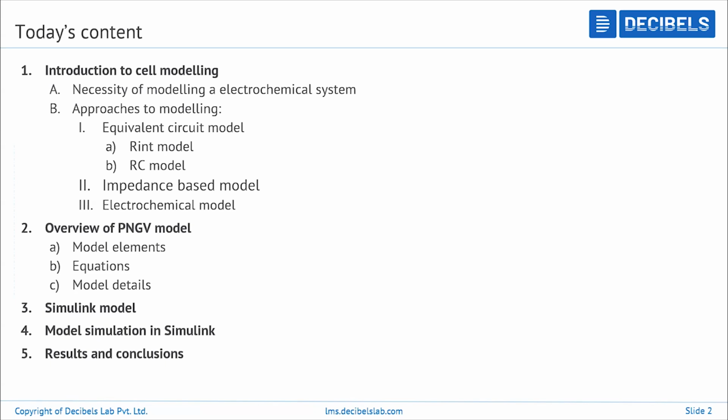Next, what process of a lithium ion cell does an RC battery model represent? Mainly we are representing all the processes inside of the cell as electrical elements like resistors or capacitors. Later on we will see how they're built. The fourth one, which model type is preferred for simplicity? Always it is electrical models. Most of the time they are very good in terms of simplicity, and they have a good balance between simplicity and accuracy,